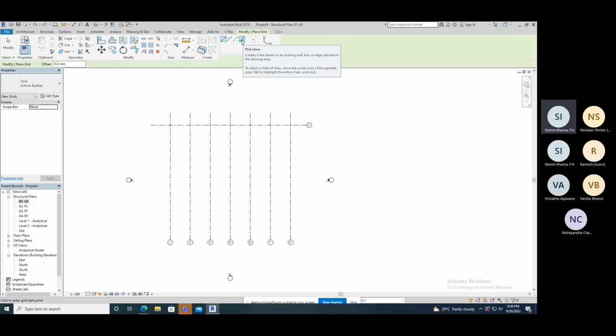One is by manual drawing. Right now I'm creating this line where we are going to create, only there it is created. But now suppose I want to create the same line on it, but I need to create an offset that is 5,000. So you can type value here, 5,000. I'm not using pick line right now, I'm using only the 5,000 value. Before this it is 0.